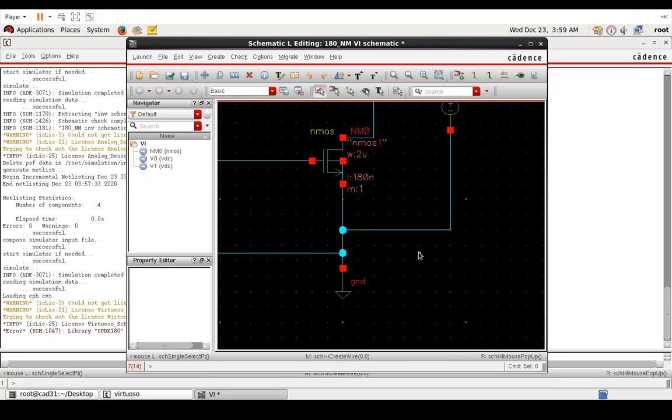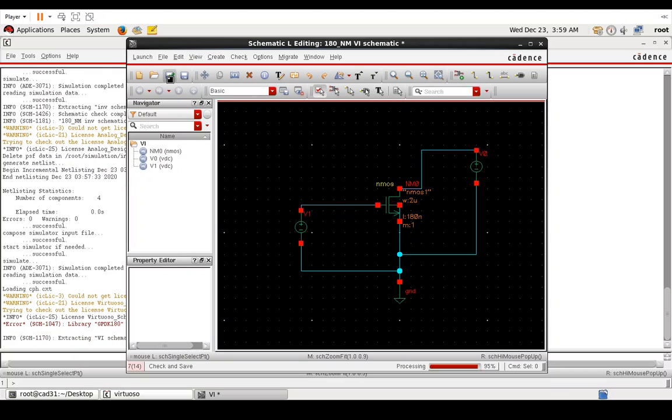Okay, so the fourth terminal, always remember, whichever transistor it is, NMOS or PMOS, connect it to the terminal where the arrow mark is there. That is the source terminal for that transistor, and the bulk and source, generally if you short them, is the safest option.